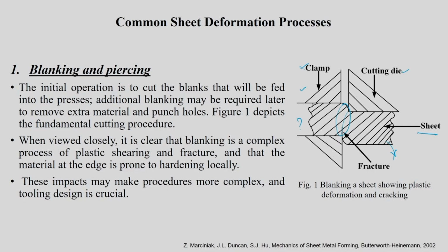If you look closely, it is actually a complex process of plastic shearing and fracture. You need plastic deformation in this clearance region. This clearance is also very important in this case, and this parameter is generally designed in such a way that appropriate cutting is done. You will see that this edge region, which is undergoing deformation, will undergo localized hardening. That is very important, and this shearing as such is not going to make a shaped component; rather it is helpful for sizing.